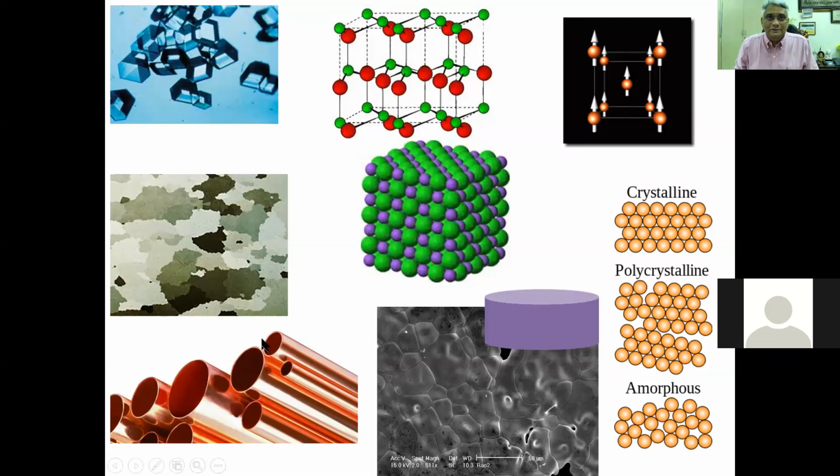Yeah. So coming back to metals, metals also have this problem of existence of different zones, except that the widths of these boundaries, what you see in metals and polycrystalline system ceramics, is quite different. As you can see here, these widths are very small. I mean, the scale is almost the same. The bar is not appearing here. But here you can clearly see, if I magnify this image, you'll find that the separation between two single crystalline zones is of the order of few microns. It starts from half a micron to 1 and above microns.